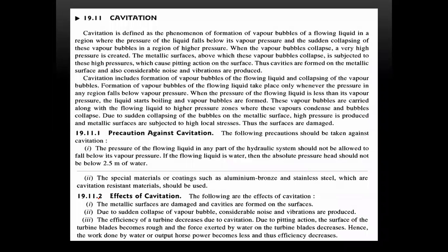Next concept in these multi-stage pumps is cavitation. We discussed cavitation in the morning and afternoon, in the first lecture. Whenever the inlet vanes are continuously under pressurized water, the water flows in the impeller and goes outside through the vanes. Air bubbles accumulate heavily at the starting point of the vane blades. Thereby cavitation takes place. Now what is the meaning of cavitation here?